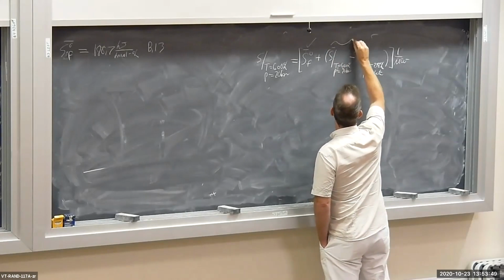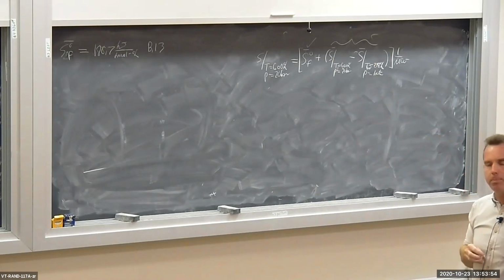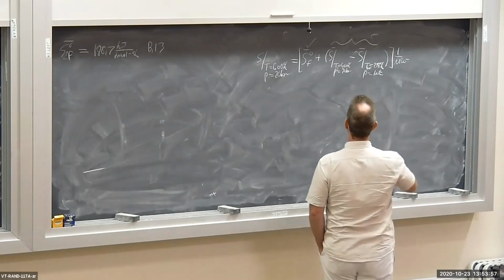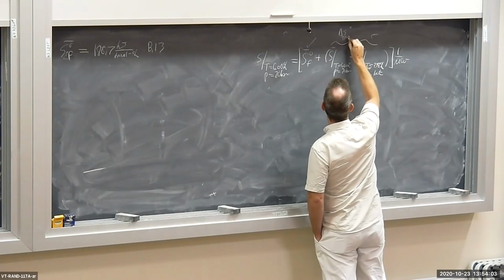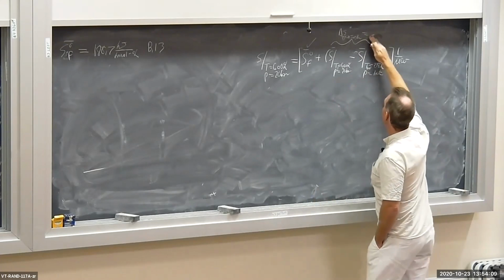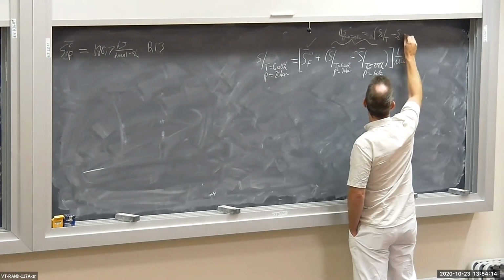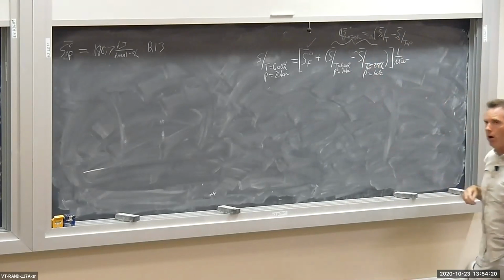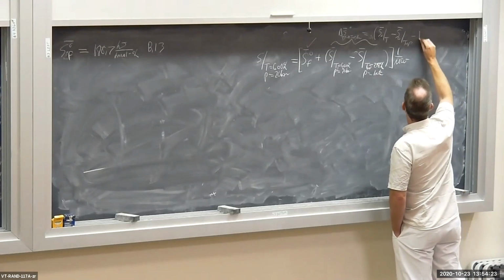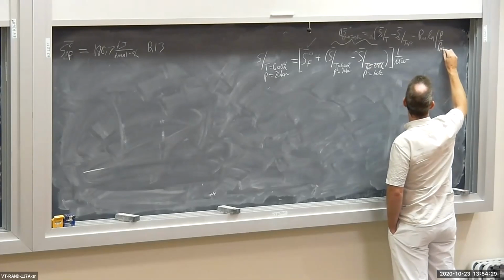So what's this delta S, or S from T and P to T ref and P ref? Well, that's going to be equal to, with variable specific heats, S naught evaluated at T minus S naught evaluated at T ref, and these are going to be barred quantities, minus the universal gas constant times ln of P over P ref.